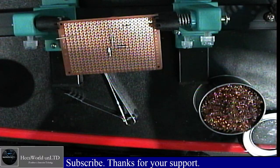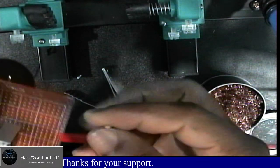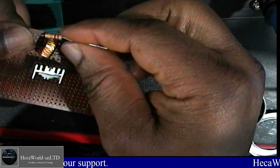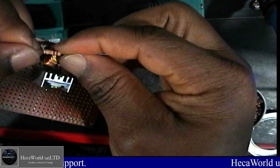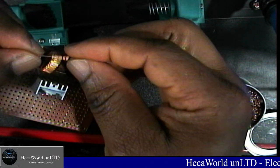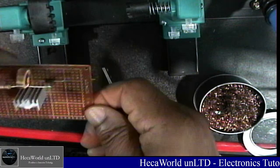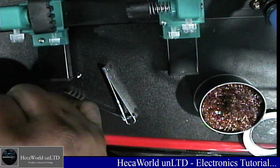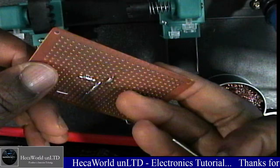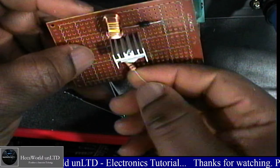Okay, now we have to turn it on to heat up. So in the meantime, we can connect the resistors. The resistors, this one here is the 20K. So you can put the 20K. And then the 20K goes from gate to ground. So gate is the first pin. So 20K goes from gate to ground.